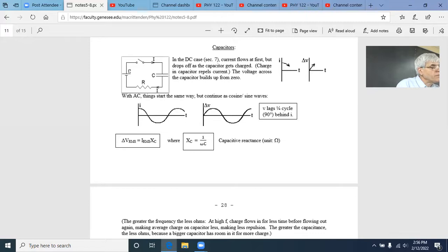Or it's a quarter of a cycle into the graph when the current goes down through 0, but it's half a cycle into the graph where the voltage goes down through 0. Again, current did it first, voltage does it later, current leads, voltage lags by 90 degrees. That makes the phase angle 90 degrees in the equation.